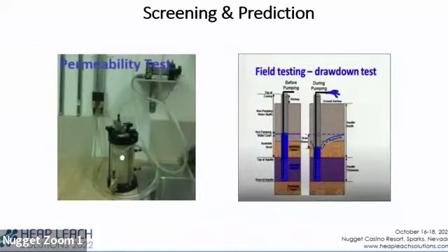Okay, so back to how do you screen this? How do you decide if you have a problem? Permeability devices are your friend here. If your permeability is high enough, you can't liquefy. If the water can get out of the way of that contracting soil as fast as it contracts, you can't build excess pore pressures. And then it doesn't matter how badly you manage the facility, you can't liquefy. You can do other things wrong, but it's not going to liquefy.